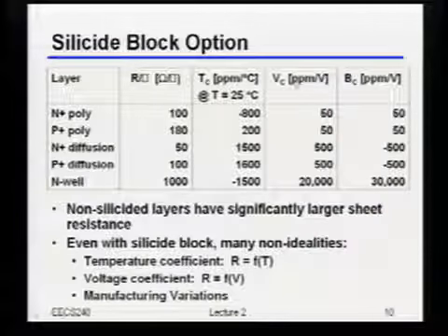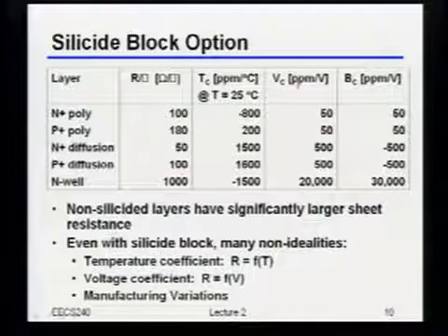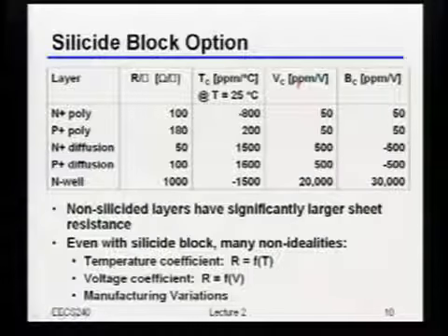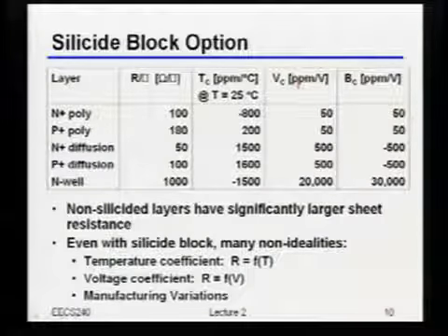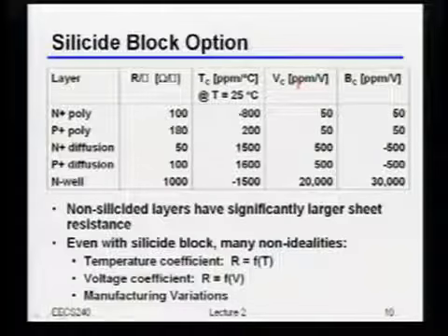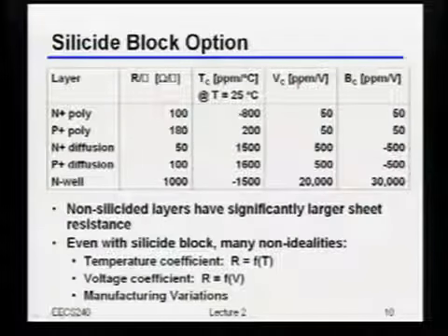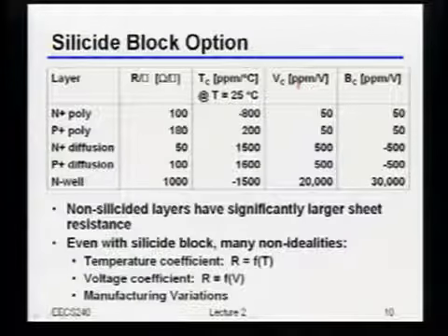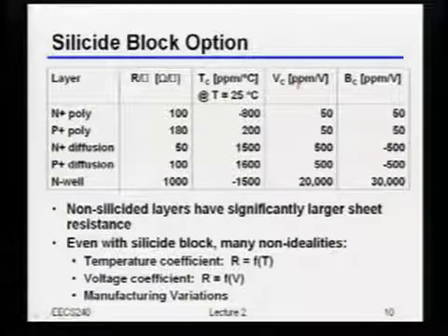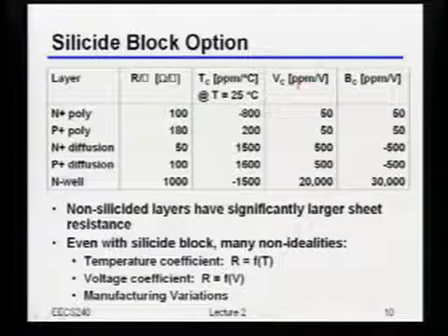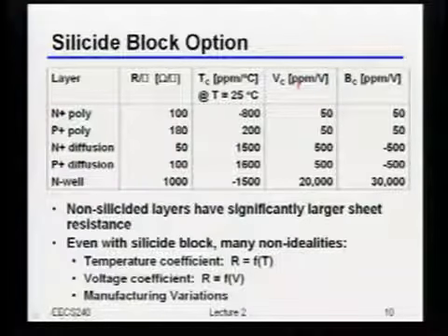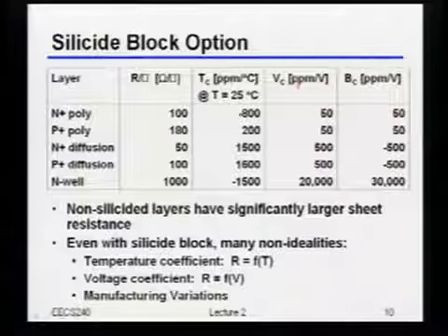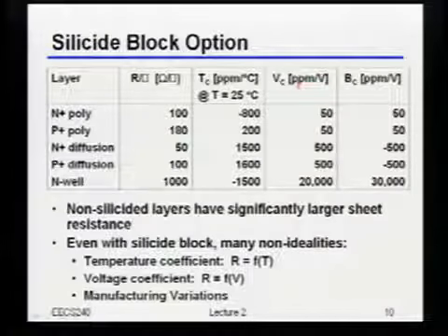These two coefficients, they have to do with the voltage across the resistor versus the voltage relative to the substrate. And again, we'll go through an example of why both of those matter one more time in a second. The other thing is, of course, none of these things are independent of temperature, right? So if you increase the temperature, then the resistance is going to change. In fact, it's more interesting than that, because not only is it going to change, but you don't even necessarily know which direction it's going to change, because it actually depends on the material.